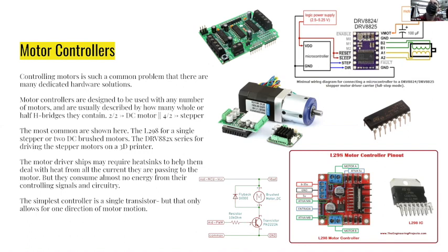And so in here, you've got a microcontroller that can tell it, would you like it to reset the stepper motor or the motor controller? Would you like to put it in sleep mode to save some energy? Or would you like it to go a certain number of steps and what direction? So just 2 pieces of information. You give it a pulse every time you want it to make a step, and then you either write it high for forward or low for backward on the direction pin. This is often handled by a library, so you don't need to know the logistics of it.